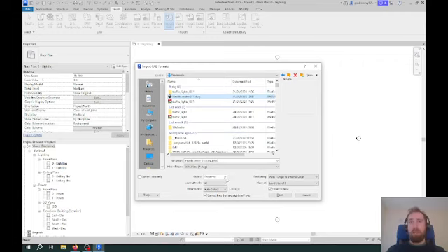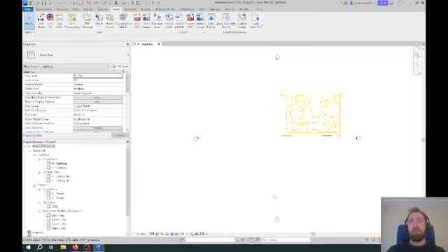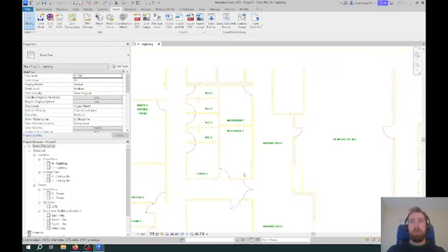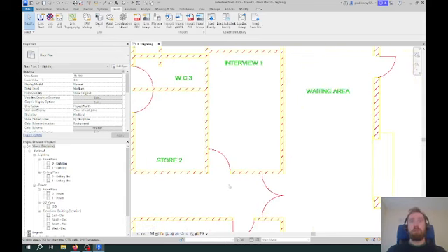Like we discussed in the class, your file will show up a preview here. But the options that we have to determine are down the bottom of this dialog box. Preserve colors, that's okay. Do we import all the layers? I suggest we do. But the issue we came to was that we leave the import unit at auto detect and import the drawing into Revit. And we'll zoom in. It'll get imported, but it will try to import the drawing based on some sort of detection of the units used.